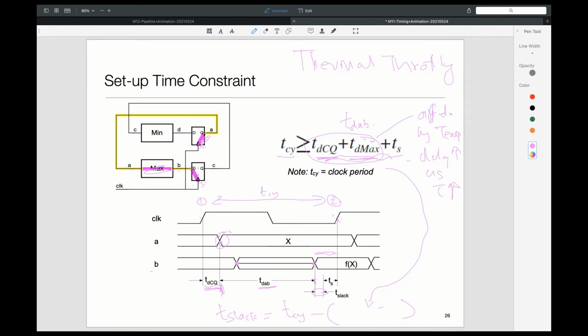They try to model how the temperature will rise and then react to it. They also put in sensors so that they sense what the right-hand side is for your particular chip at that moment in time, and then set the clock rate accordingly. Some of the more modern, cutting-edge systems even make use of fancy AI and machine learning algorithms to do it.